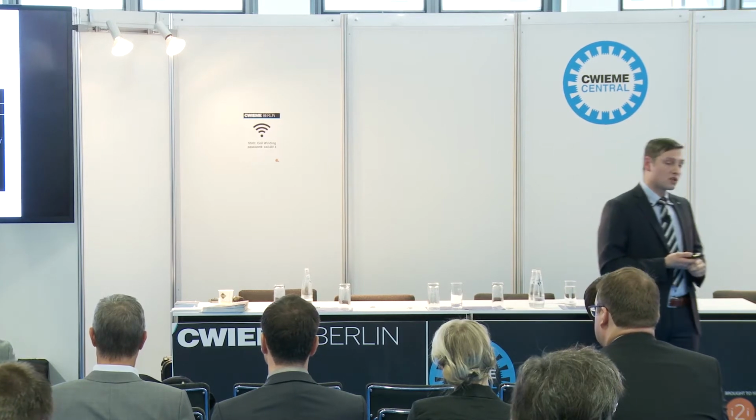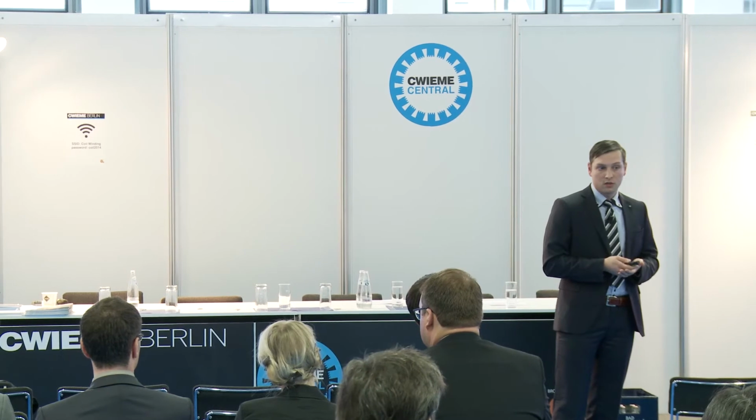The laser fusion cutting was done with a conventional cutting machine, well known in industry and applied for cutting stator and rotor laminations. Here we retrieved the signals from the axis drives. These signals tell us exactly where each drive is as a function of time. And so we can calculate velocity, accuracy, cycle time, and cutting speed.